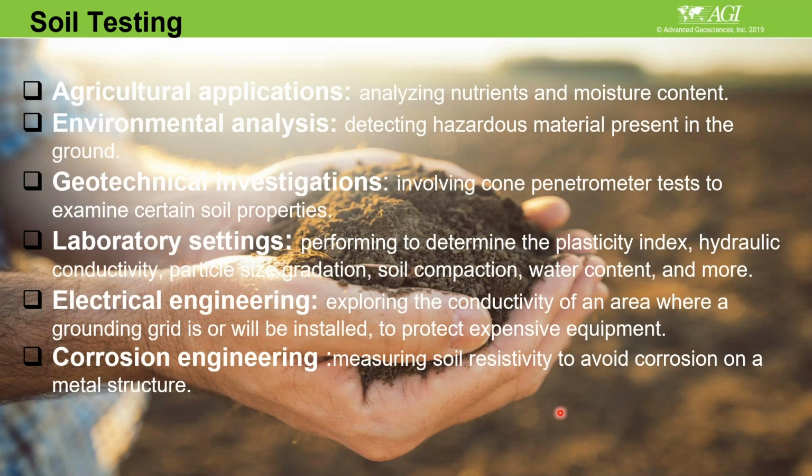You can also do laboratory testing to determine the index of the soil, the salinities in it, the mineralization in it. You can get a soil sample, and there is a soil sample box for the 4-electrode measurement. You just put in your soil samples, preferably in situ, but you can do it in the lab also, to get the resistivity of the soil samples.